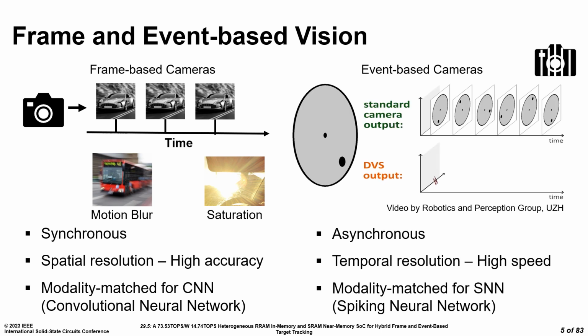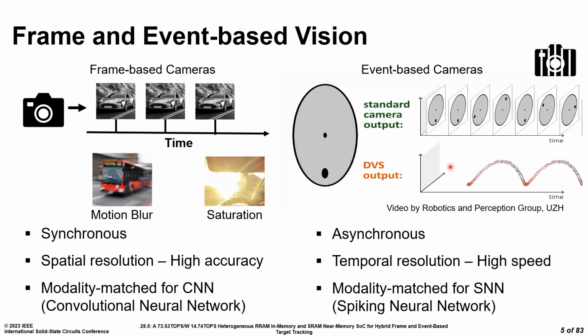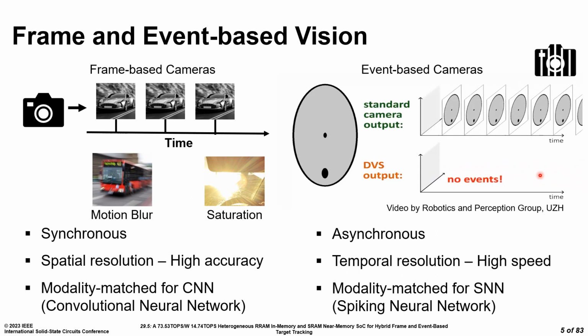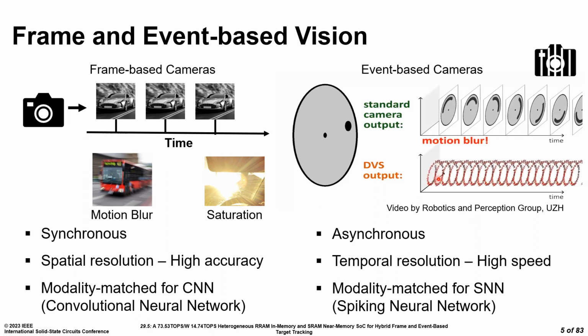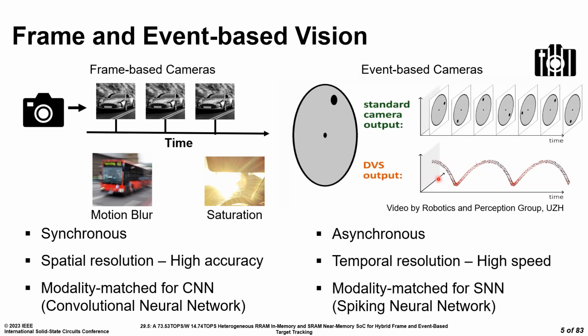A high-speed alternative to this are recently popularized event cameras, which are shown here. These cameras capture change in intensity of a pixel instead of the absolute intensity. This video shows a rotating disk with a dot on it. The standard frame-based cameras capture discrete image frames. The event-based cameras, on the other hand, capture an asynchronous stream of events when the intensity of a pixel changes. As there is no redundant information about the stationary background, detailed temporal information can be packed on the bus.